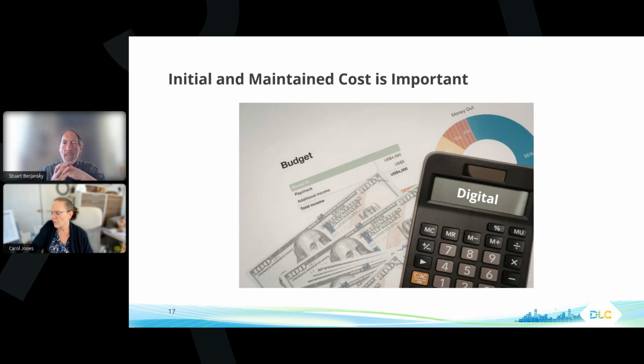Yeah. So there are some mythologies about DALI, and one of them is that it's very complicated. And it used to be that flexible sort of equaled complicated, right? Before we had digital systems. Now, having a lot of features and having things that could be considered complicated, it's really not that way, because the interfaces figure all that out for you. Just because it's powerful and advanced, it does not mean that it's going to be difficult. I'll give you an example. When you're installing DALI, you don't have to worry about the directionality of the wires. You don't have to worry about polarity. It is actually a very simple installation, and more cost effective.